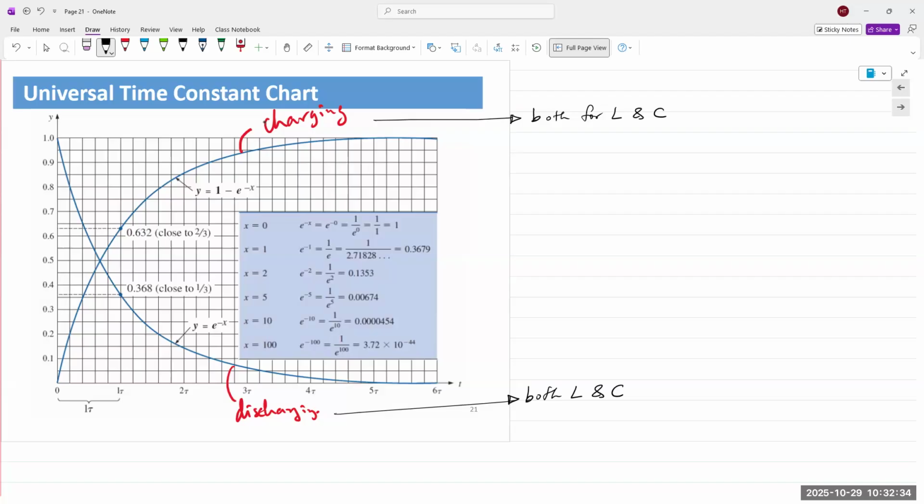All of the touchscreens that we use in modern electronic devices are capacitive touchscreens. So when we touch our fingers onto the surface of the touchscreen, there's a digitizer on there, there's a sensor on there. And what it does is it measures capacitance across the surface of the touchscreen. And with our fingers, when we touch it, it changes the capacitance that is measured.